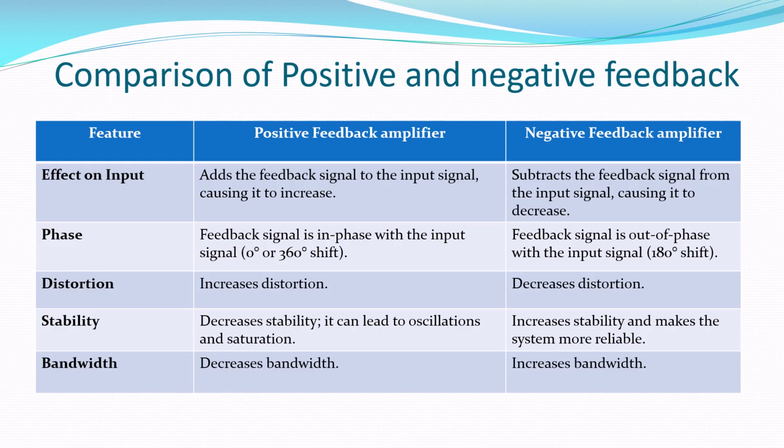And next, this is the comparison of the positive and negative feedback amplifier. As input, we are applying a sinusoidal signal. In the positive feedback amplifier, the feedback signal is added to the input signal, causing an increase in the level of the signal. In the negative feedback amplifier, the feedback signal is subtracted from the input, causing a decrease in the signal.